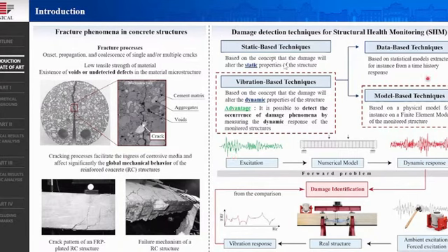and that the adoption of damage detection techniques decreases the risk of catastrophic failures. Therefore, structural health monitoring is gaining more and more importance in the last years. For instance, the vibration-based technique, founded on the concept that the damage will alter the dynamic properties of the structures, represents an effective tool to detect the occurrence of damage phenomena by measuring the dynamic response of the monitored structure.